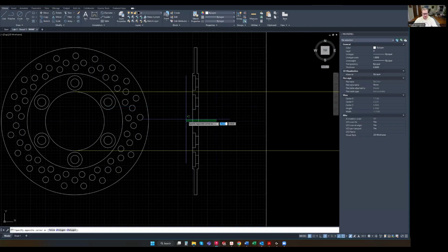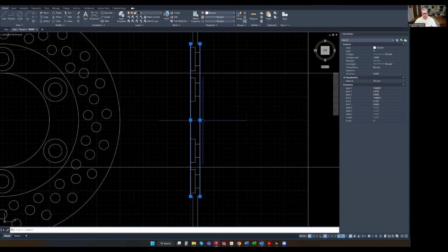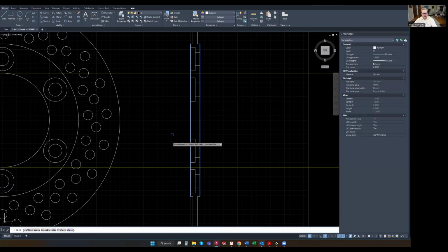So these guys, I'm going to use the power trim tool. I'm sorry, I'm going to use these as a cutting tool and use our more advanced trim tools. So I'm going to highlight both of these, type TR, enter. And then now I can trim these off and it'll trim everything on either side. And remember, if I'm just using the power trim tool, if I don't use something as a cutting tool, it doesn't know where I want to stop the cut.